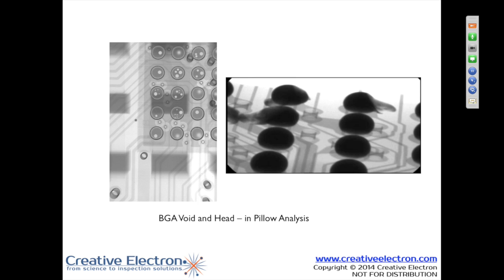You have a database of images and a database of results, and you can compare those images and results to the point that you're able to look at the image and say, yeah, we had that problem once before, tie that image back to your database, and say, that was definitely this issue. And a lot of times you can see your process drift by looking at the X-ray images. Your process hasn't failed at that point, but you do have a drift, and that drift is easily corrected prior to sending bad boards out the door.